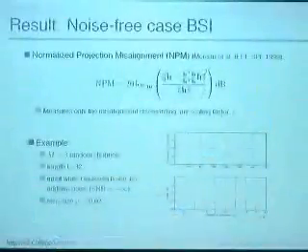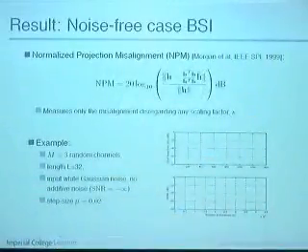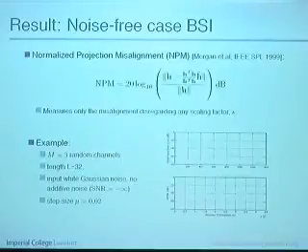So now if you look at a quite ideal example with the frequency domain adaptive algorithm, you have 3 randomly generated channels, fairly short, 32 taps. Input is white Gaussian noise, and there's no additive noise. So what do randomly generated channels mean? It just means you have some random taps that you generate. So it's not room acoustics. The impulse response is random. The impulse response, yeah, exactly.